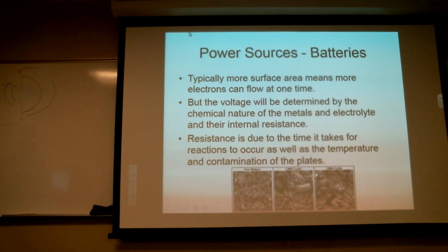The upside of the NiCad battery is there are instances where you need a whole lot of current, like starting a turbine engine. That's where we use them a lot in aviation. Well, we finally got pretty good at making lead acid batteries that can do that. And frankly, NiCads are a total pain in the butt to maintain. So as far as I know, they're not being used in aviation anymore. There may be some out there.